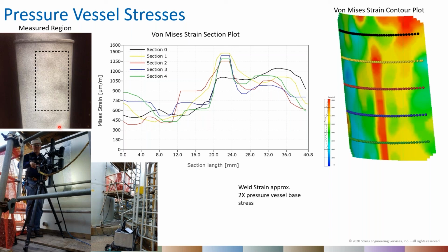And another advantage of that is we were able to find, once we looked up and down this pressure vessel at the welds, the areas that had the peak strain concentration. And from then on, we knew that if we ever needed to go back and inspect those welds, that would be the best place to look first because it's where the highest stress concentration is.